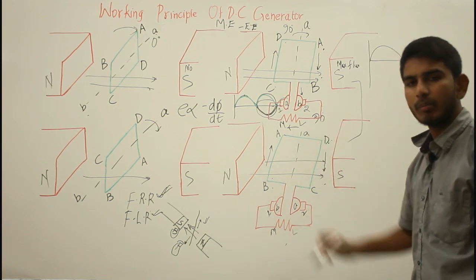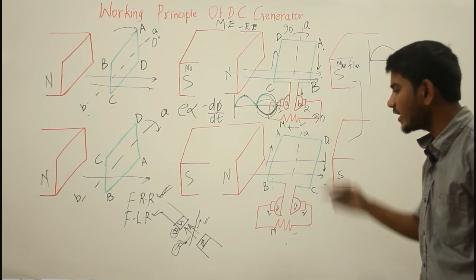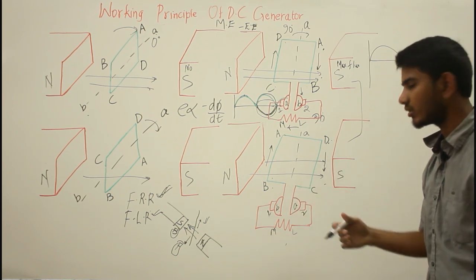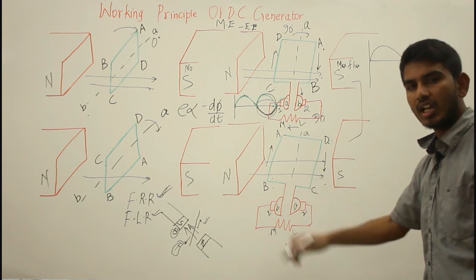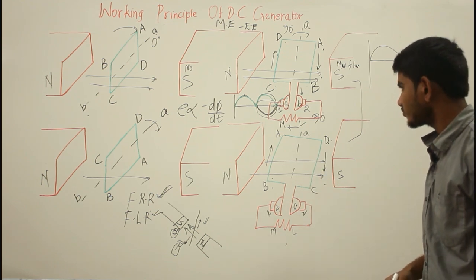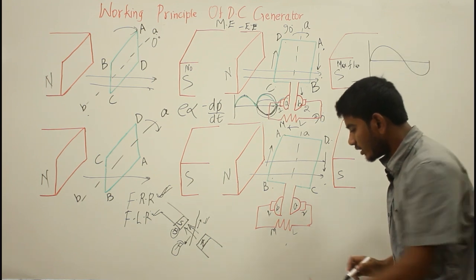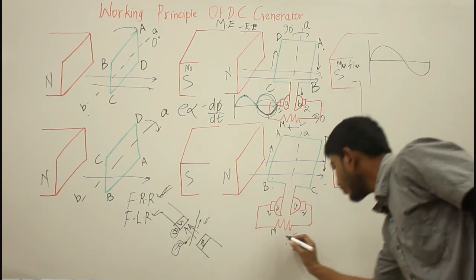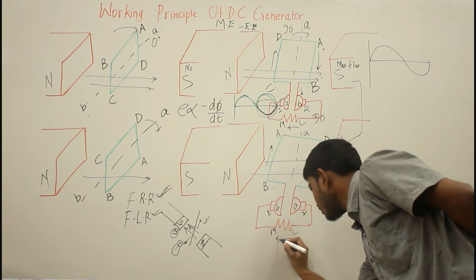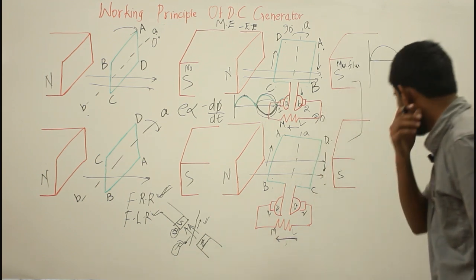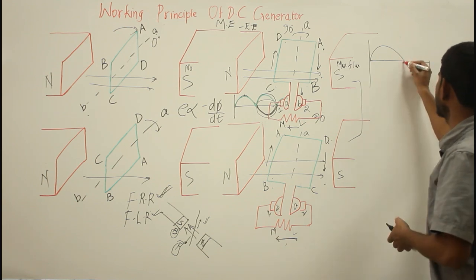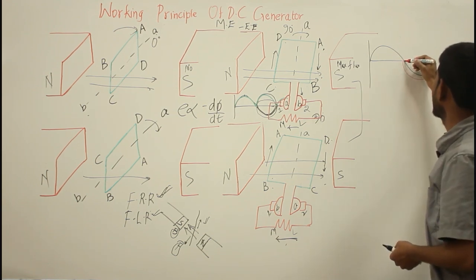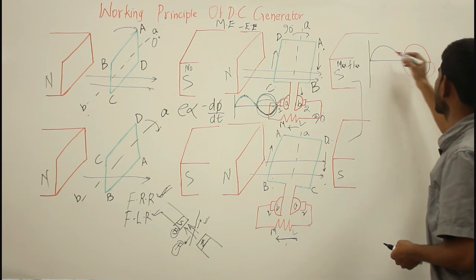So I know the current is reversed, and if I again reverse the armature terminals with the help of the commutator segments, then I can again see the direction of current flowing from L to M. So this reversed current is going to get altered into my positive direction.